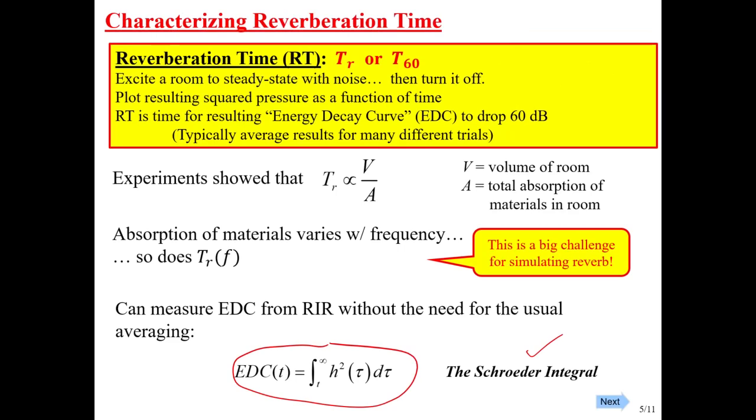Well, based upon that idea, we can then take the EDC measured that way, and instead of putting it into the EDC Schroeder integral, we're going to take the impulse response that we can measure, and we now go back to Unit 1. We learned about a very nice way to measure the impulse response of a room. Nice dodecahedron speakers running exponentially swept sine waves, doing inverse filtering, and all that gives us a very nice measurement of H.